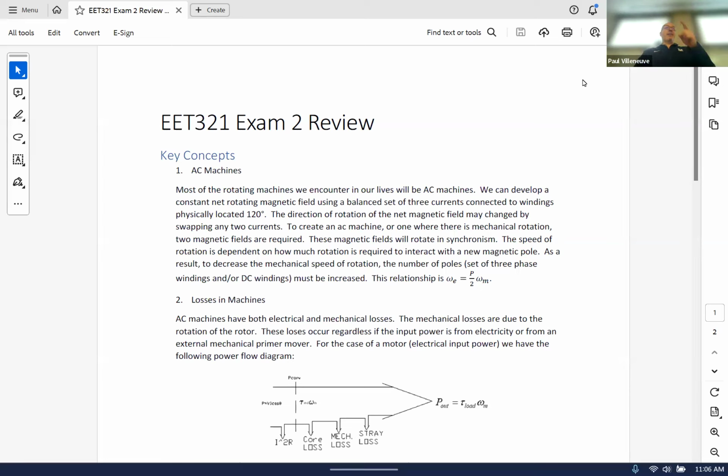So we actually got this nice magnetic field, which, remember, when we talk about magnets, if we have two magnetic fields interacting, we can take advantage of those to actually cause something to rotate. So the concept of electrical machines is we just get this magnetic field rotating around and we're going to chase it. And the speed of rotation was determined by the number of magnetic poles, not the number of wires, because we already start out with 3 wires, but the number of poles is we're going to end up having a second set. Here's a key thing, a second set of windings, so that now we can get another magnetic field that originates inside there.